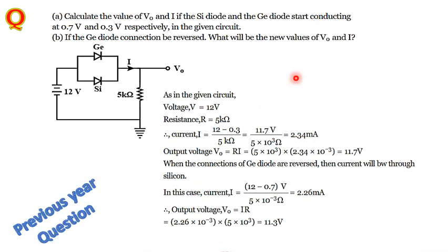According to Ohm's law, hope you remember this one, E minus V is equal to I into R. From here, I is equal to (E minus V) divided by R. We used to mention this in the previous problems. You just go through that one. So current I is equal to 12 volt minus only 0.3 volt. Hope you remember this one.